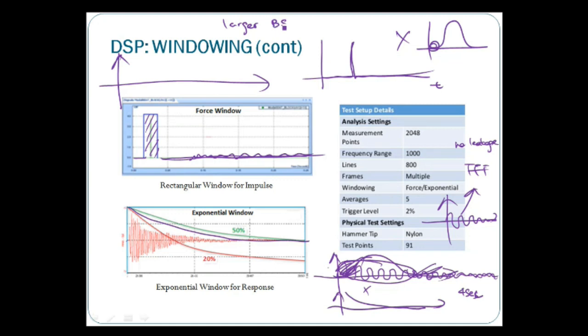If you have a larger block size, then your data acquisition time for collecting the samples for the FFT is longer. Of course the signal will go down. Maybe at 4 seconds it is still not yet 0, so maybe after 8 seconds it only comes to 0.